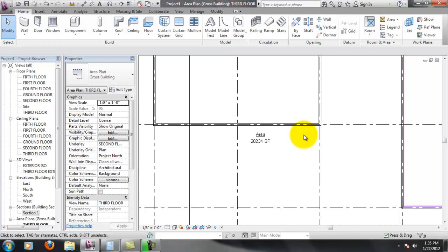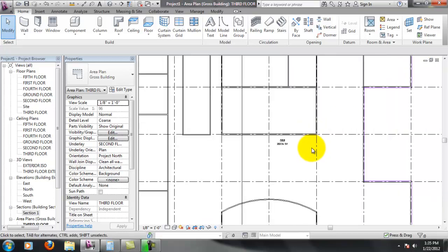But what I basically did was in the actual building codes book, if you go to the means of egress section of the code manual, and I believe, let me see here, table 1004.1.1 in the 2006 IBC, it's going to give you a list of floor area per occupants, and basically I classified this building as a business type. So what that gave me was 100 gross square feet per person.